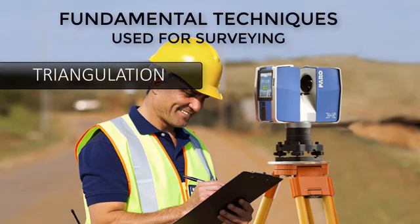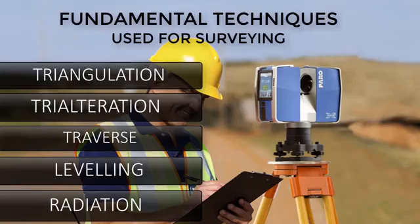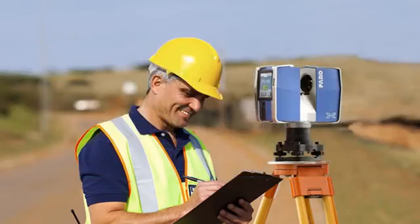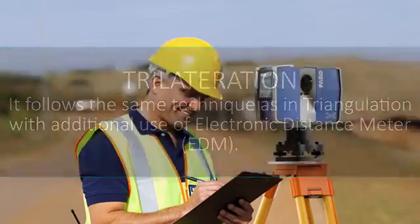Fundamental techniques used for surveying are triangulation, trilateration, traverse, leveling and radiation. Triangulation: in this technique, numerous triangles are interconnected and overlap to measure angles from a surveying station. Trilateration: it follows the same technique as triangulation with the additional use of an electronic distance meter.